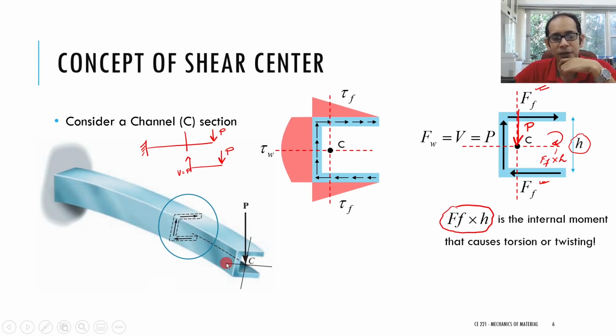I can have some kind of attachment or configuration where I make the line of action of P, and as you can imagine, instead of applying this P to the center, I apply it over here. Suppose I'm applying the P over here, let me hypothetically draw it. This P is always going to be there to balance out the externally applied load. So if this P and this applied P over here cause an anti-clockwise moment, that can help in resisting this clockwise moment over there.